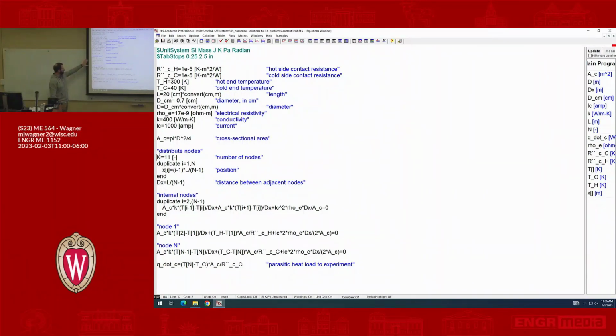And in EES, what you're going to do is use a duplicate function. How many of you know what duplicate is or have used it? Okay, not everybody. So what EES does is this is essentially like a for loop for EES. Really what it's doing is it's taking this equation that you've put in here, which is x, and then the square bracket with some index i. And then there's some function that depends on i in some way. And you're taking the contents of the duplicate loop and you're repeating it as many times as it takes to get across this range from 1 to n.